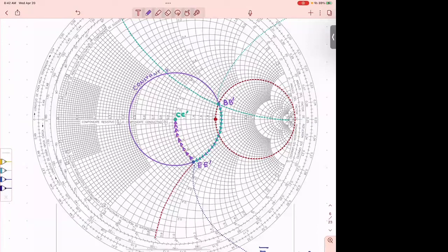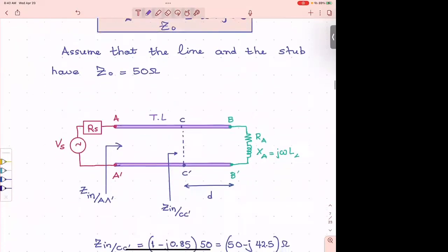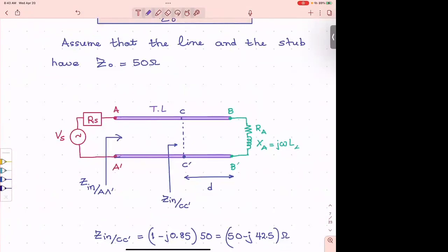Because on a transmission line, what did we say everywhere on the line? Anywhere on a straight transmission line, if the line does not have anything added, the magnitude of the reflection coefficient is constant. Did we say that? On any simple section of a transmission line, the magnitude of the reflection coefficient is constant, which means the VSWR is constant.